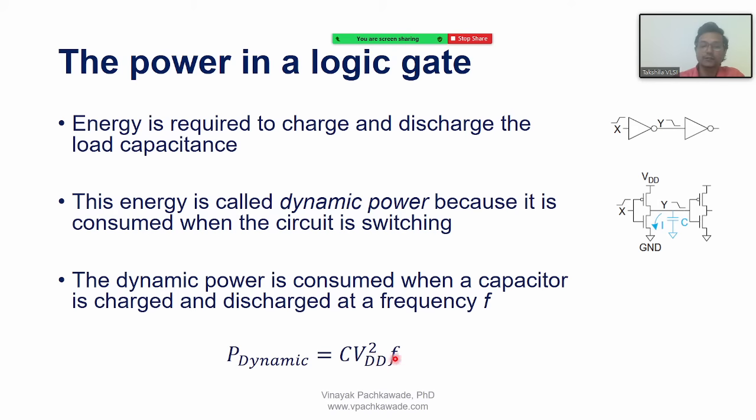So, square of the VDD. And third, if the switching happens faster, it means if your circuit is speedier, then power cannot be that low. So you see now, if the speed of the circuit increases, power also will increase. So remember this equation, even when you draw the layout and do some physical verification, you need to know this equation. Sometimes it will help.